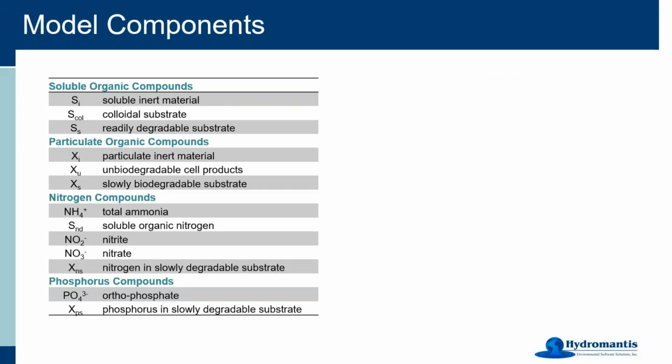Again, even though our main importance is physical-chemical treatment in water treatment plant systems, we still sometimes encounter, for example, ammonia or nitrates coming into your system, and in those situations you want to do some biofiltration, or utilize some of the biological processes. To address that, we allow you to have some inputs with respect to the organic carbon coming into the plant.